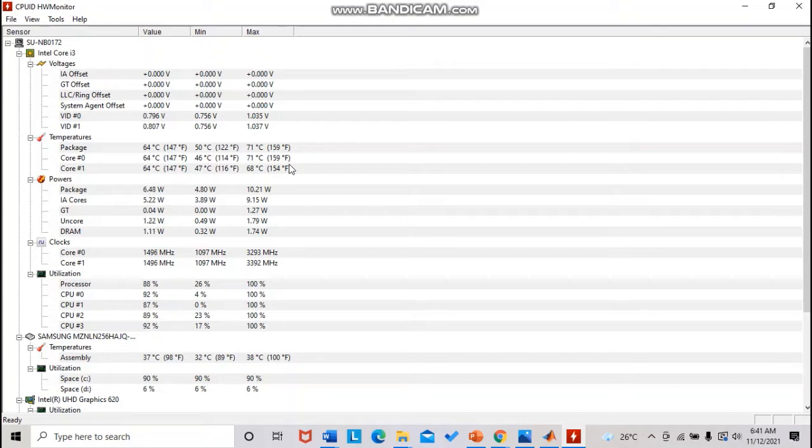In addition, if the initial temperature of this experiment is not high enough, we can use the Prime 95 software to add load to the CPU. Therefore, it can help the laptop temperature increase. In this experiment, the two scenarios place the CPU under load with the laptop cooling pad. And here is the Prime 95 software.